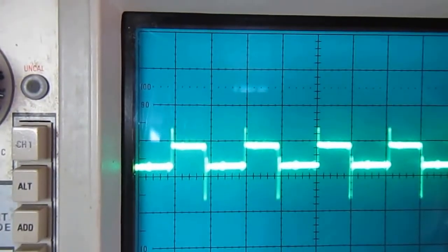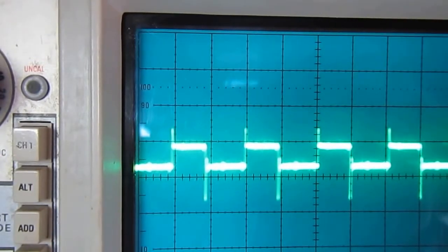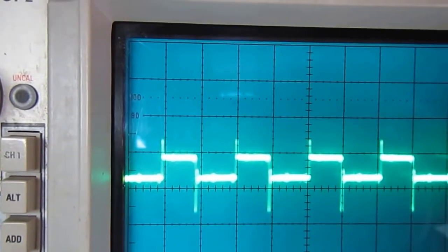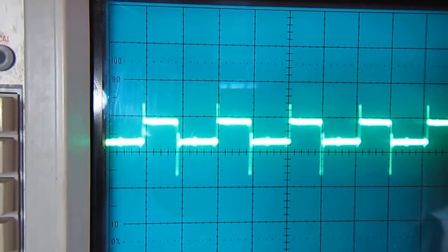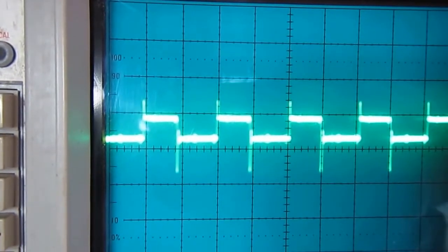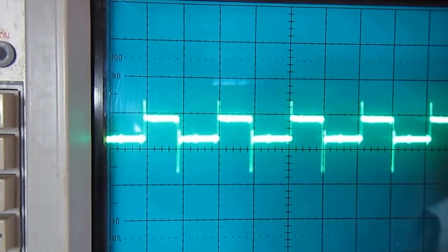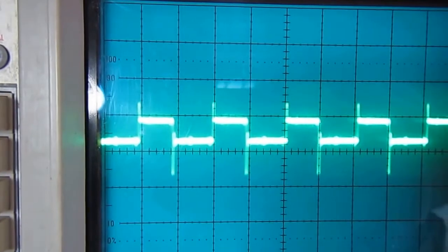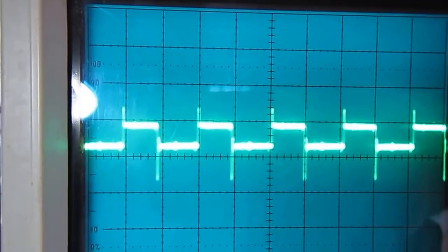That means this chip is trying to drive a shorted line. So some of the RAM on this address are shorted, probably to ground. So we'll try to identify what chips are shorted to ground in this C64.